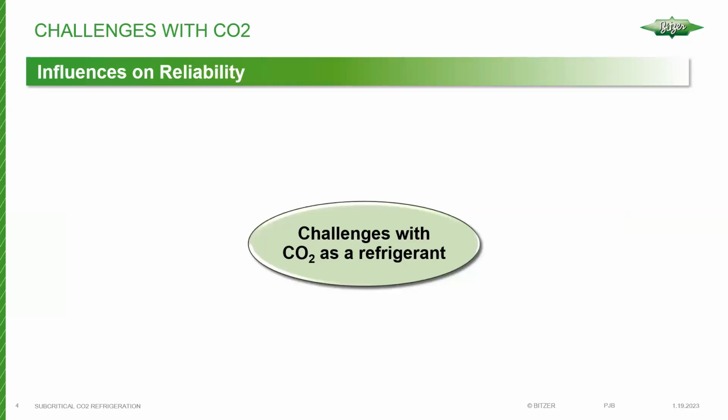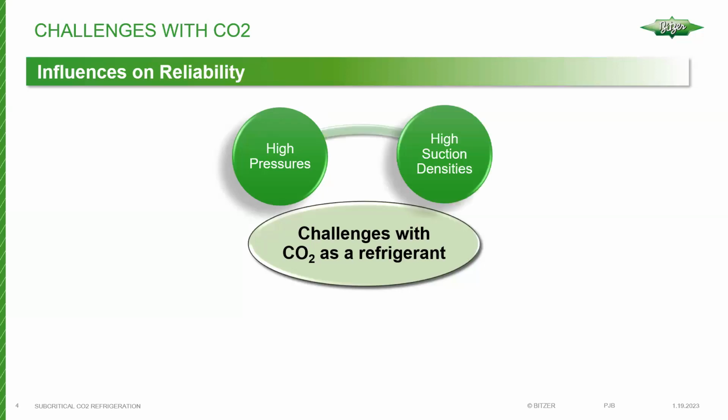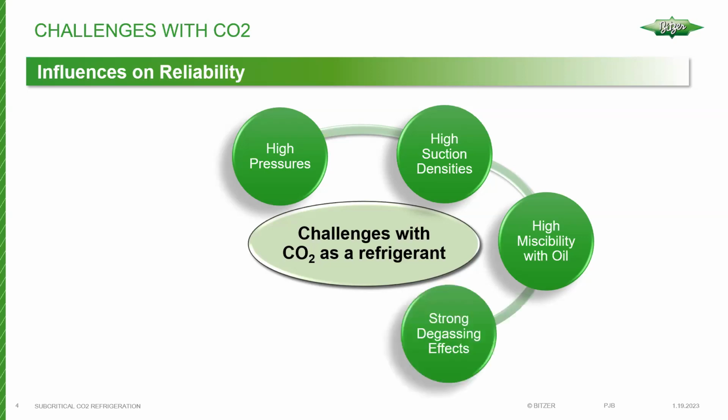Back to compressors. First of all, it's important to understand that, generally speaking, there are challenges when using CO2 as a refrigerant. For example, most of us, I'm sure, know that CO2 exhibits quite high pressures compared to a lot of the refrigerants we're used to working with. High suction densities, high miscibility with oil, which is often a challenge. Even with HFC refrigerants and POE oils, we had a fairly high miscibility situation, but with CO2 and POE oil, it's even more challenging.